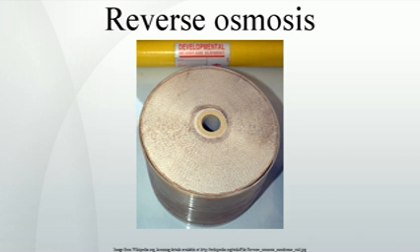Additionally, the ultrafiltration permeate, which contains lactose, is concentrated by reverse osmosis from 5% total solids to 18 to 22% total solids to reduce crystallization and drying costs of the lactose powder. Although use of the process was once avoided in the wine industry, it is now widely understood and used. An estimated 60 reverse osmosis machines were in use in Bordeaux, France, in 2002. Known users include many of the elite classed growths, such as Chateau Lafite Rothschild in Bordeaux.